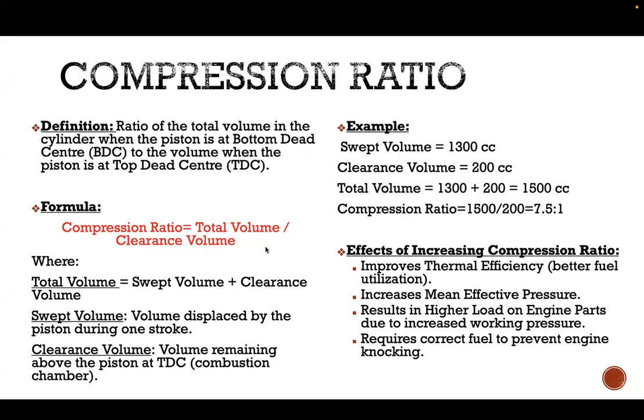So why is your compression ratio very important? The greater the compression, the more efficiency our fuel is going to give us. It increases our thermal efficiency. That means our mean effective pressure is going to be higher. So this is going to result in a higher load on your engine parts due to high working pressure.